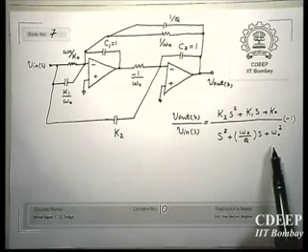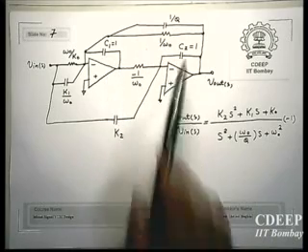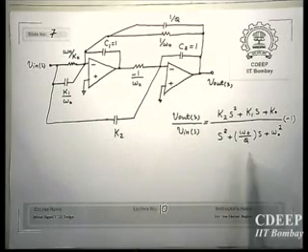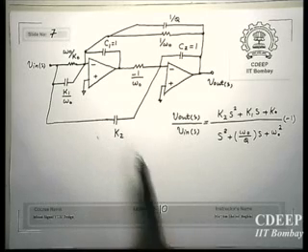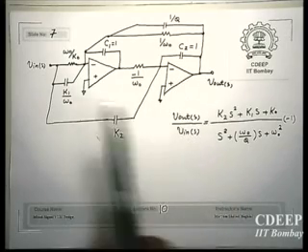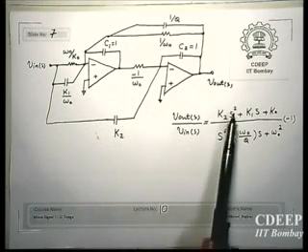Then your denominator, which is again second order, is controlled now by this RC feedback, and here C1 and C2 are 1. Of course, notice here you have 4 capacitors, but order is 2 because you have 2 loops made by capacitors. So 2 capacitors eventually are made because we want to create zeros. Now by this normalized value, exactly you see how value of components determines transfer function.